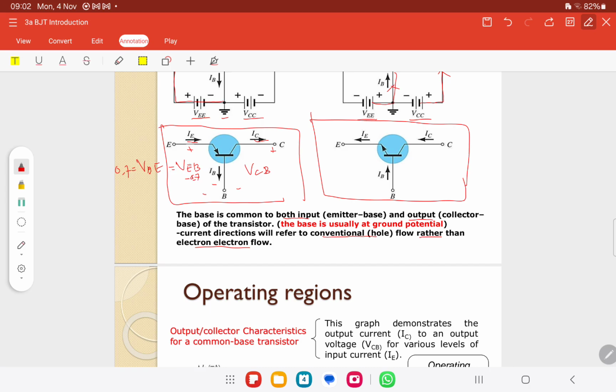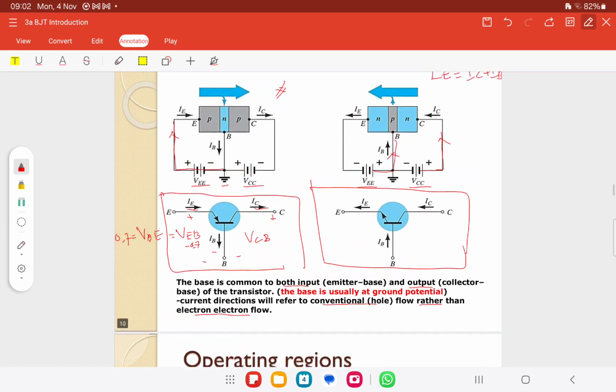Okay, it has to be reversed because usually we have the base on top and the emitter at the bottom. So that is for VBE, base on top. Usually it is like this: base, emitter, so this one is VBE. In this one the emitter is on top and the base is at the bottom, so it is reversed, VEB. It's like we measure at the same node but reverse its position. That's why we get the same value, but it has minus 0.7 volt.